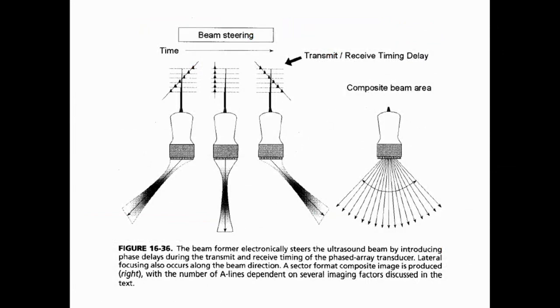So this is what I'm showing. With all of those, 128 elements or 90 elements or whatever it is, you can set the delay on those. And that's what they're trying to show up here. What they're showing on each one of these lines is, when do you fire the pulse? So if the pulses are firing sequentially from left to right in sequence, then you can have a beam that's actually shooting off in this direction. And that's just because the wave fronts from each of those line up. Just by shifting the phase delay here, you can actually make the beam shoot out the other way.